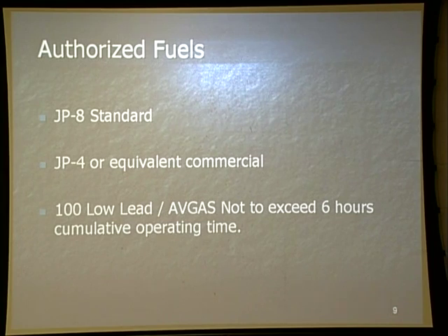Now, why did we go from JP4 to JP8? Does anybody know? Higher flash point. It's a safer fuel, which is why we went to it. But that's why when we talked about engines, we talked about that liquid-to-liquid cooler and what it brings to the table.